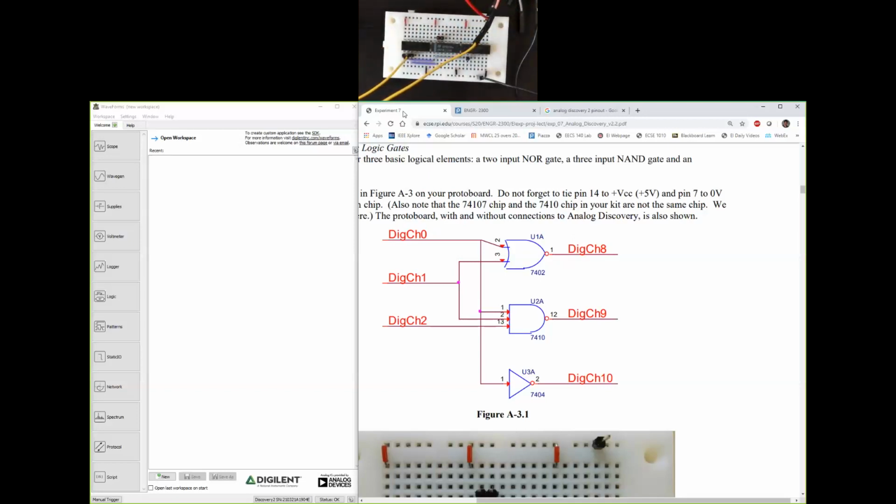The next one is going to be pin 3, channel 1. So 3 is green. Pin 2 was channel 0, I did that. Pin number 3 should be connected to channel 1. Channel 1 is the green wire.